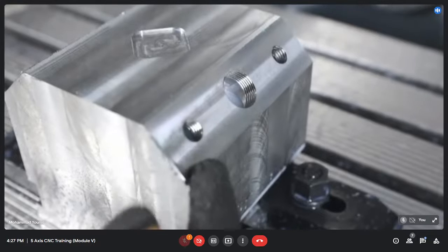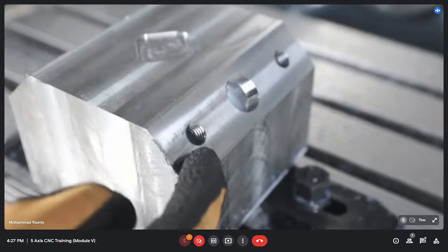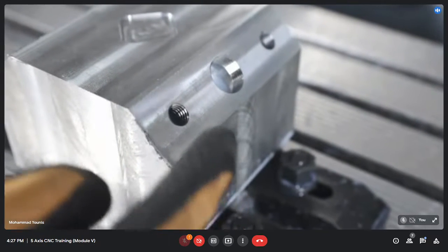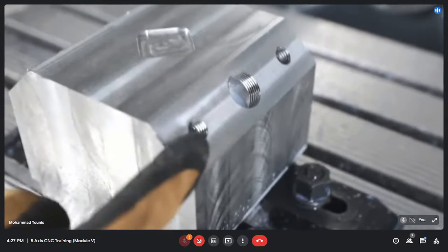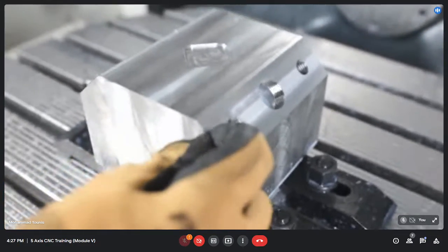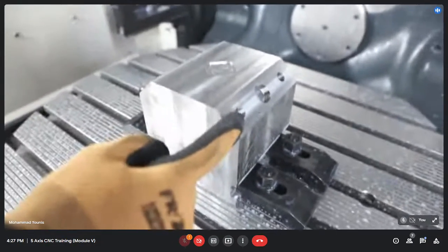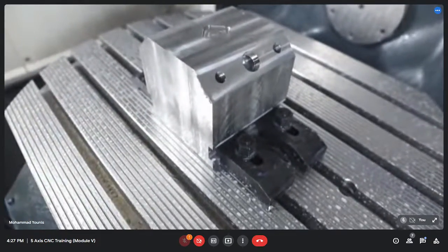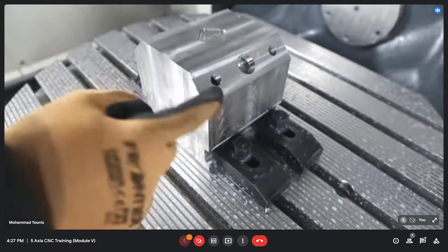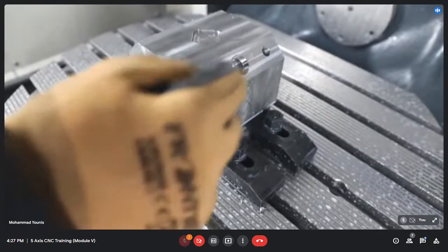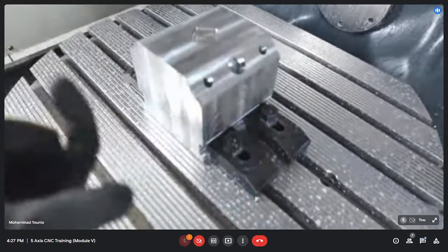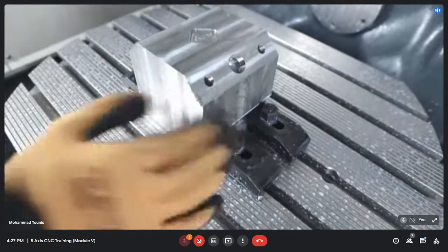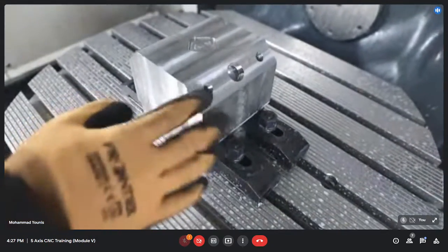Similarly, here we first have drilled a hole, so a drilling operation is performed here. Then we have enlarged that hole with the help of an end mill, and at last we have performed a tapping operation here. So here also you can see that we have threads on the internal periphery. The difference is that the tapping tool just goes in and comes out. So whatever the nominal diameter of the tap is, our threads will be of that diameter.